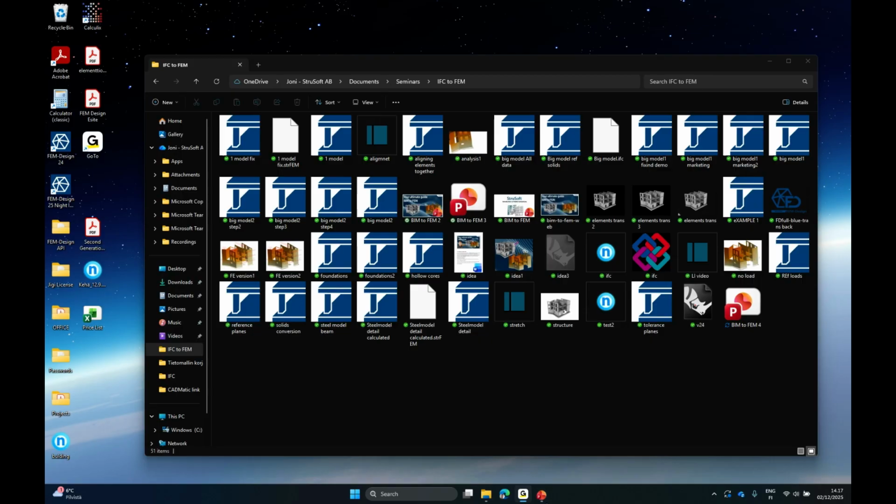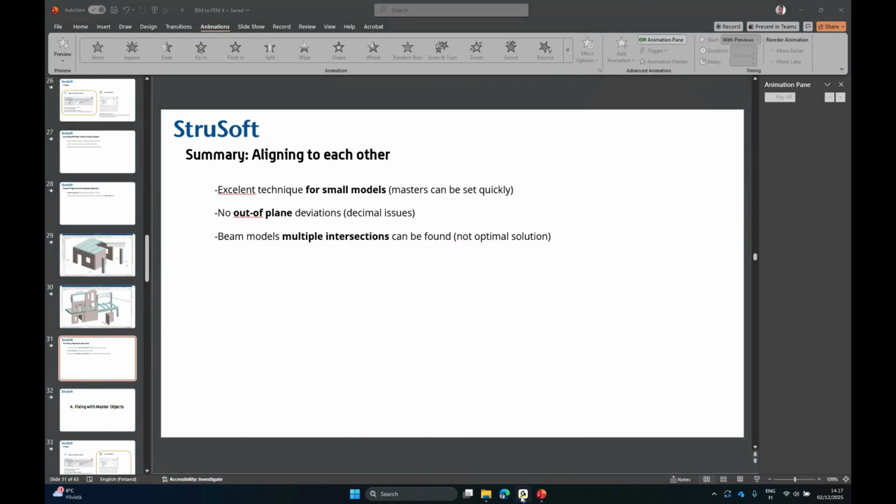So do you have any questions so far? Oh, there's one question. How can we deal with a slab at a different level, like one slab is 50 millimeters above slab 2 and we don't want them to be at the same level? Then you actually have to put a really low tolerance if you want to preserve that 50 millimeters. Yeah, and we can connect them together. Actually, there's a line connection if you want to preserve that 50 millimeter deviation, but usually 50 millimeters in big models is such a small deviation that it's reasonable to put them in the same plane.